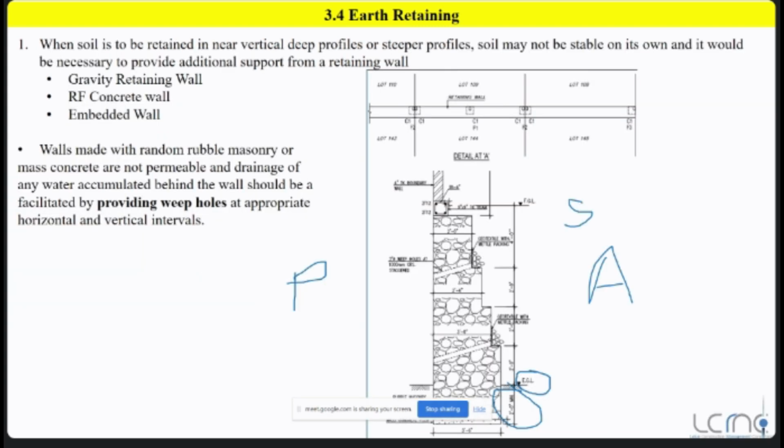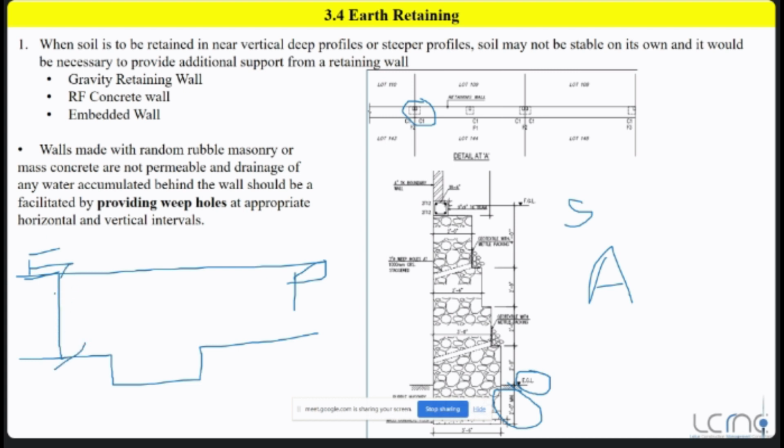Clear? Now I have taken the longitudinal section here. If you take this longitudinal section you can see the column locations. In these column locations, if you construct, now this is your existing ground level, this is your EGL. If your foundation is like this, your column is going like this. Okay, now this is 2 feet, this is 2 feet, and this will be 3 feet.